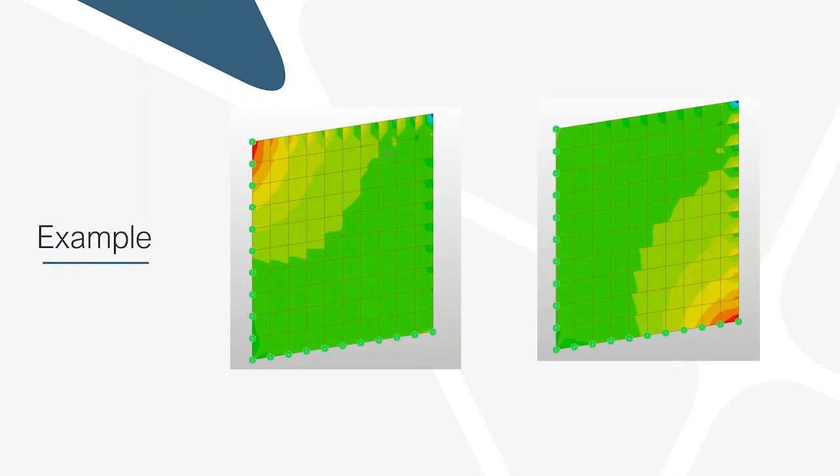And then this is a really basic example that shows how boundary conditions can create force concentrations. The bottom corner of this example is extremely stiff because you're fully fixed along two edges. And so when the top corner of the plate is displaced, the bending moment concentrates near the top left and the bottom right corners. And this behavior is real in an idealized world, but the actual behavior of a structure can definitely vary. So for example, if this structure was made out of concrete and you developed a large force concentration near the top left corner or the bottom right corner, which is also extremely common in problems where you have openings with sharp corners, the force will concentrate. And will it actually concentrate like this in the real world? Likely no, because the concrete, if it concentrates that high in those areas, will start to crack. And when that happens, the boundary conditions change in real time and the forces redistribute.